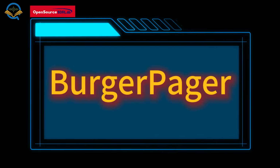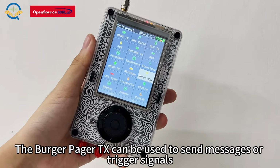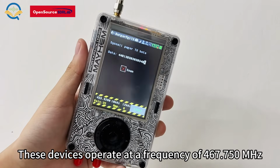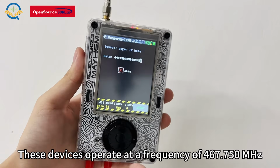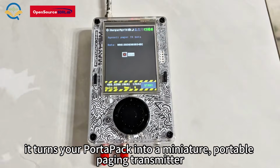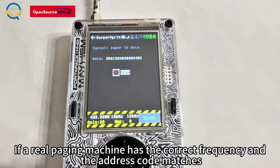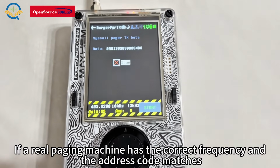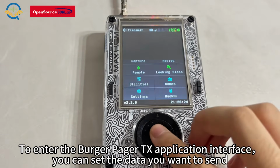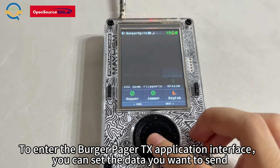Burger Pager. The Burger Pager TX can be used to send messages or trigger signals to the restaurant's intercom system. These devices operate at a frequency of 467.750 MHz. In simple terms, it turns your PortaPack into a miniature portable paging transmitter. If a real paging machine has the correct frequency and the address code matches, it will receive the message you sent and ring. To enter the Burger Pager TX application interface, you can set the data you want to send.